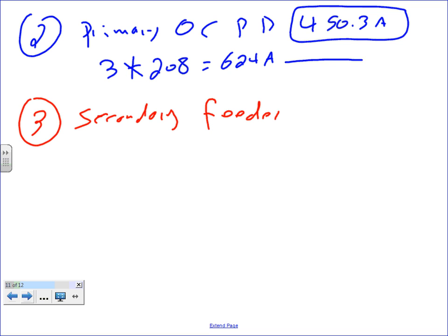And guess what? You're going to go to 240.6. And from there, if you read note number 1, it says if it's not a standard size, you can go up. You don't have to, but you can go up. So what's the next standard? 700 amp. If it's not a standard, what do I do? I can't emphasize that enough. I always write it down. If it's not standard, you go up. That's my symbol going up.